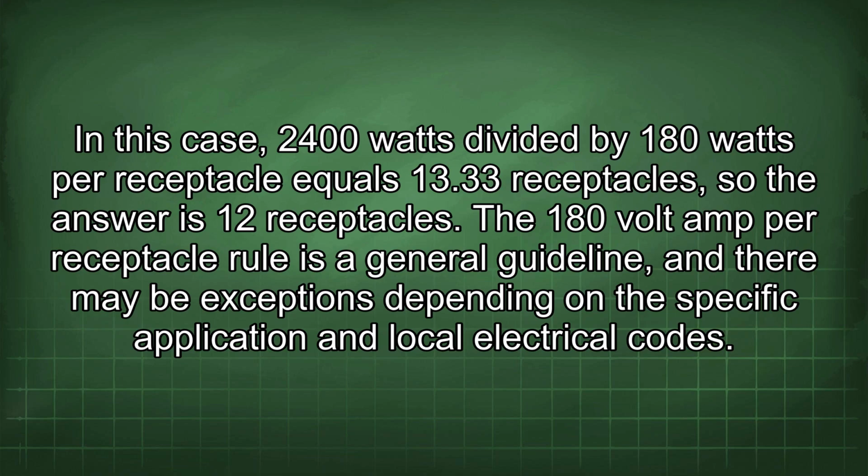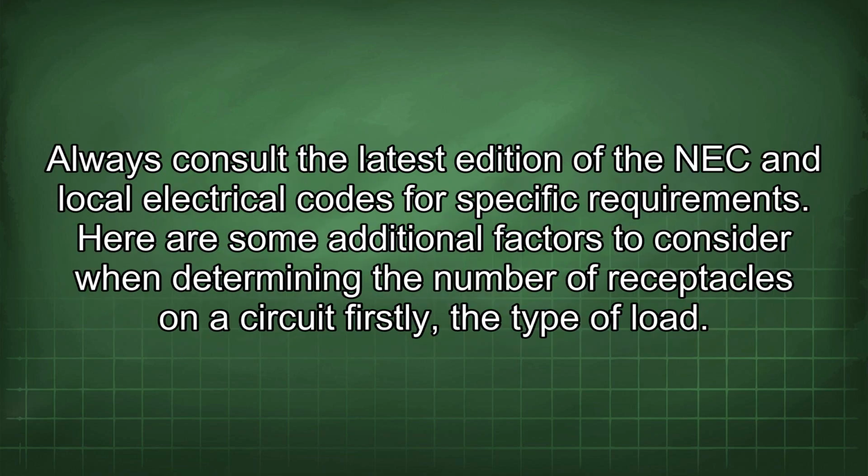The 180 volt amp per receptacle rule is a general guideline, and there may be exceptions depending on the specific application and local electrical codes. Always consult the latest edition of the NEC and local electrical codes for specific requirements.